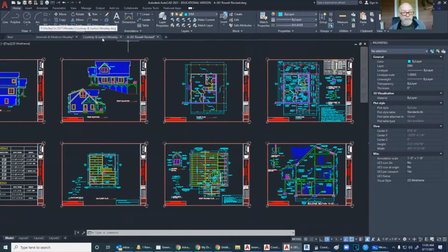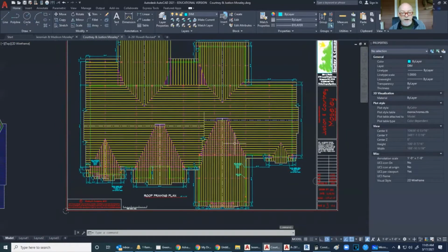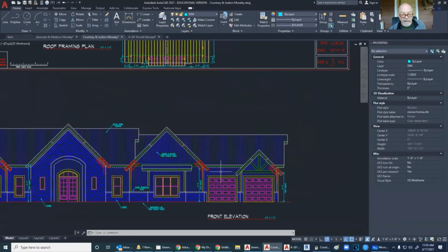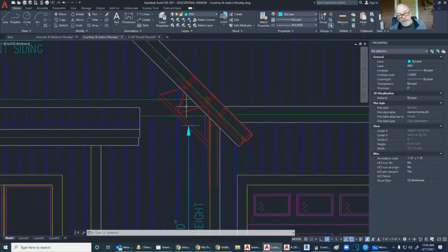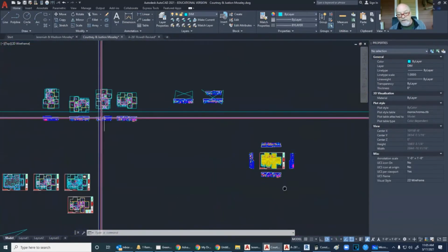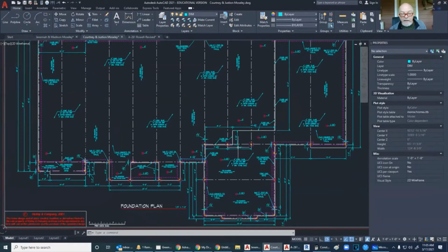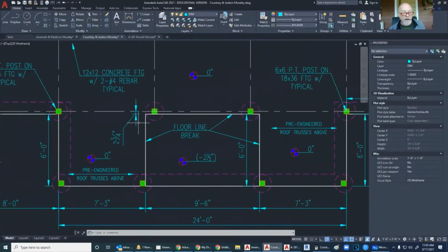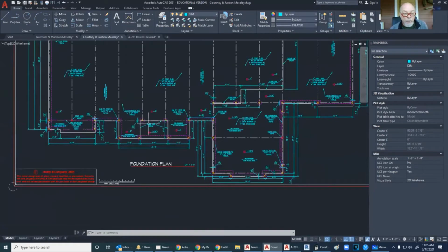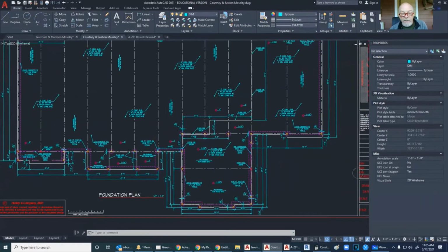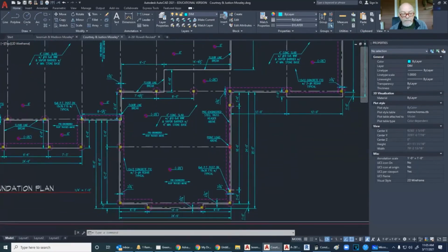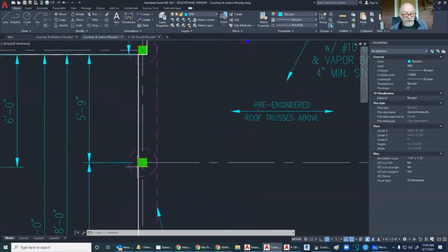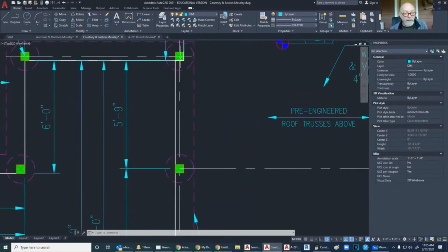Now, when you get into much more complex systems, such as this house here, this house is using a different type of method of framing. They're using steel trusses on posts. So in this particular house, we had to plan out where our posts were going to go. And they have to follow this to the T when they lay out for their foundations, when they lay out for their wall framing, everything, so it will run out, because typically there's no studs in between this, I mean, we're going to put studs.